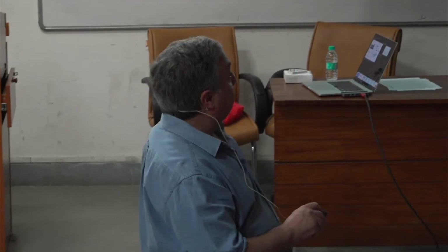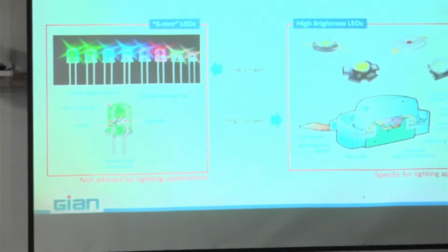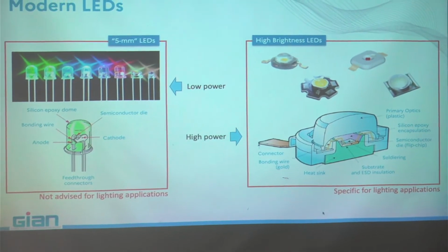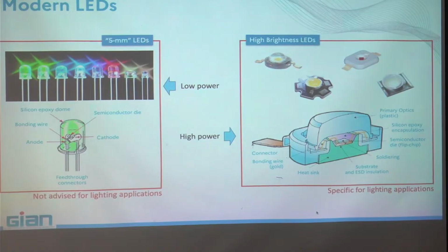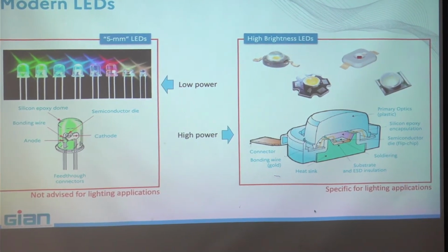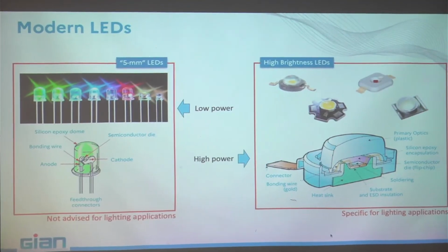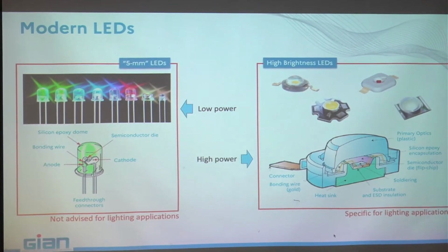But finally, the 5 watt technology has been abandoned because it's very difficult to produce good quality chips for 5 watts. You need a larger surface, and the efficacy is much lower. Today we mainly use 1 watt chip technology, and inside a single module you can have maybe 50 chips, and in that case you have a 50 watt LED.